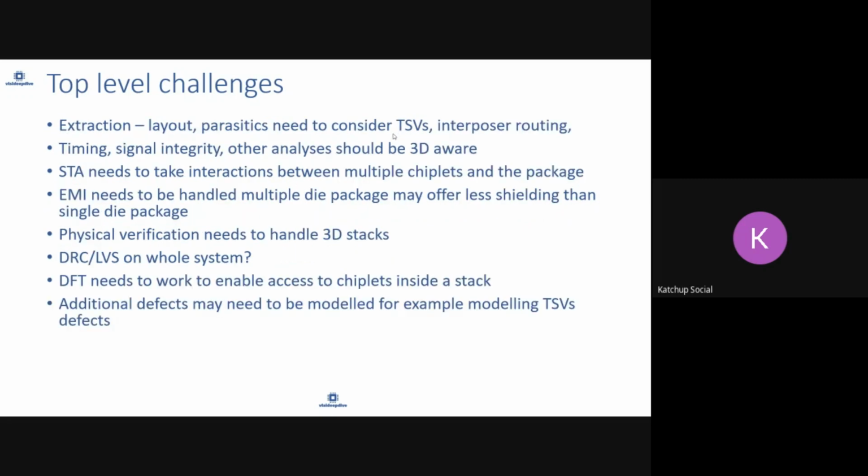So top level challenges, for example, extraction, like layout parasitics, need to consider TSVs, interposer routing, even for timing and signal integrity. All these analyses need to be 3D aware. Static timing analysis needs to take interconnection between multiple chiplets and package and should be able to do all this analysis. Your EMI needs to be handled with multiple die packages, and that may offer less shielding than a single die package. Physical verification needs to handle this 3D stack.